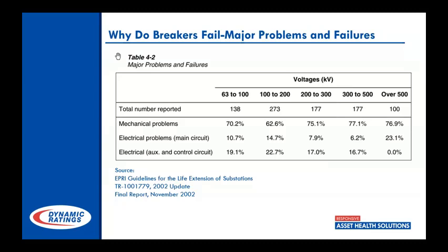So when we start talking breakers, we're talking a lot of linkage, lubrications, that kind of thing, and that's going to be in large part why we will have these breakers that won't operate. And like I said, every time we have one where a breaker fail occurred, or there was just a failure to operate, oscillography gets pulled, everybody pours over that. We start trying to figure out exactly what went wrong in that instance. Maintenances are scheduled and that type of thing.